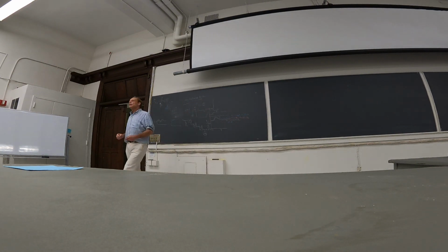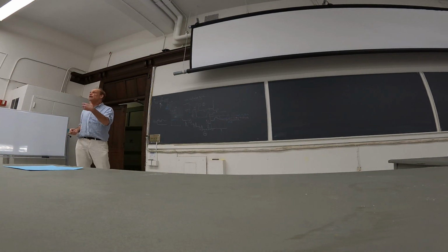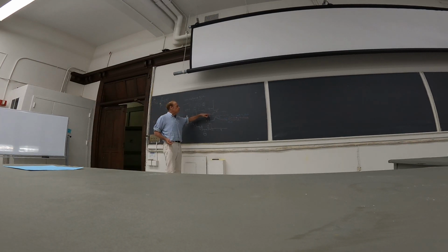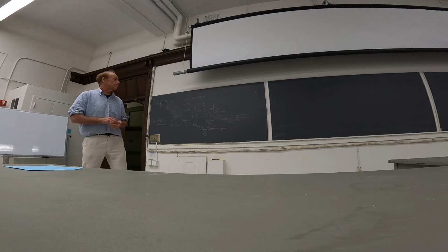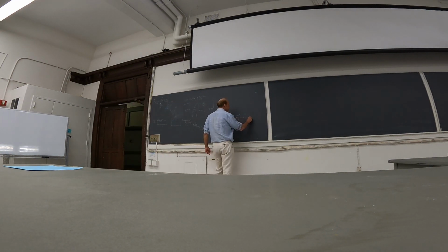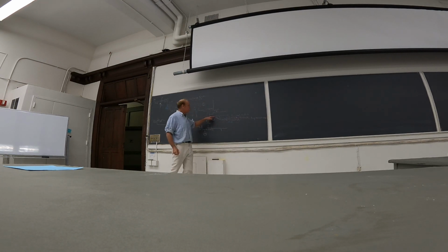But what you can see here is that in order for the feedback to actually kick in, to really work, it has to wait a while until the error builds up. So when the output is only a little bit off, feedback isn't doing much because there isn't much of a difference between the instantaneous value and the desired value. We don't really get much of an effect of the feedback until there's a big difference between the actual value and the desired value. So even with better feedback, we can get big excursions. This is an excursion.